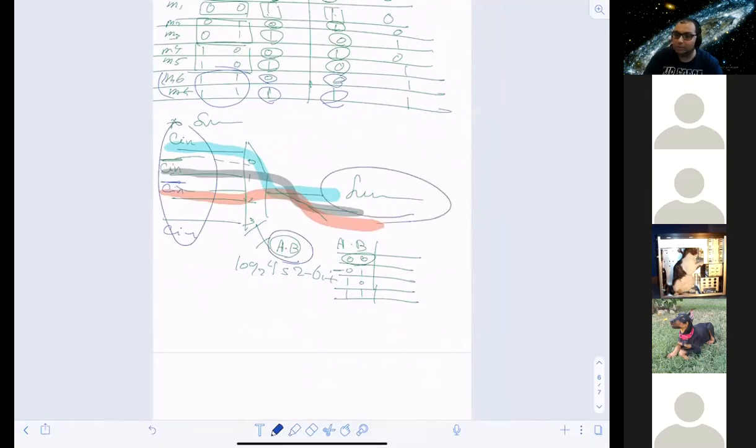So pretty much by using AB as a controller, using the Cn as an input of the multiplexer, the output coming out of this multiplexer will be performing summation. So this setup in front of you is the summing of the 1-bit full adder. So did you see what I did?